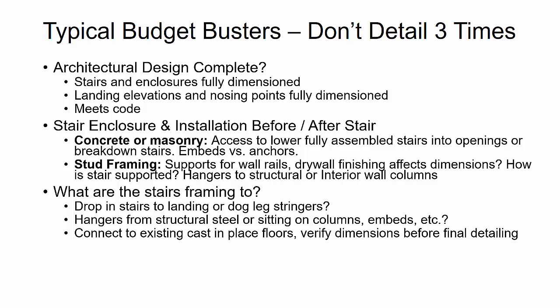Then you just have to look at whether or not you're going to be doing hangers from structural steel, or are you going to be sitting on columns, or are you going to be expansion bolting your stairs or wedge anchoring or attaching to embeds that are in concrete. And you also want to check that if any of your stairs are connecting to existing cast in place floors, like from the structural floor system, you definitely want to verify dimensions, especially opening dimensions, before final detailing.